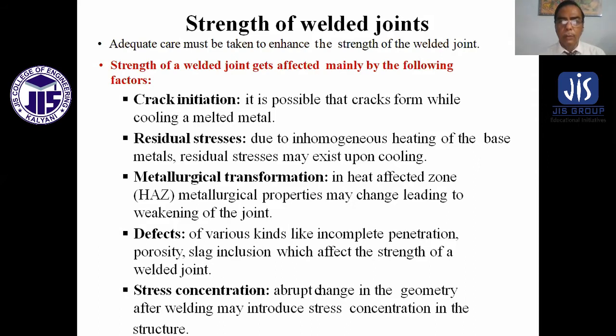Residual stresses due to inhomogeneous heating of the base metals: residual stresses may exist upon cooling. Metallurgical transformation: in the heat-affected zone, metallurgical properties may change, leading to weakening of the joint.